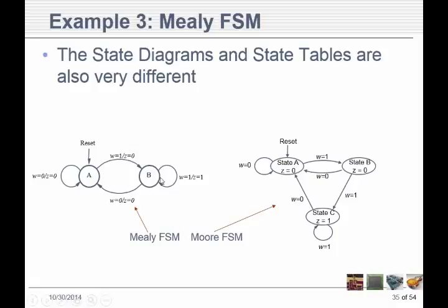Right? Here I've got Z is associated with W's a 1 and it's in state B. So that does help a little bit. I've got to be in state B and W has to be a 1. And we don't need a state C anymore. Now if we see a 0, then output goes back to 0. So it simplifies things a great deal.